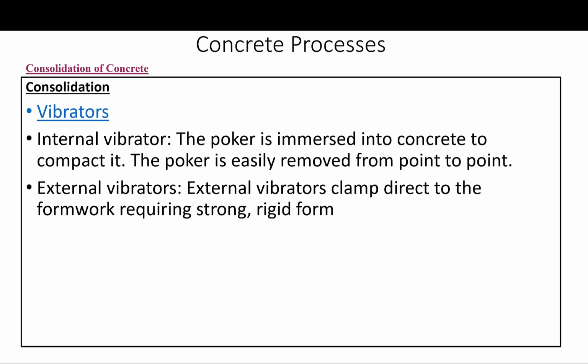Okay, vibrators. So vibrators can be external or internal vibrators. Internal vibrators, the pokers are immersed into concrete to compact it. The poker is easily removed from point to point. The external vibrators are clamped directly to the formwork. These will require strong, rigid forms. And again, before using external vibrators, you better make sure your form can handle it. You don't want to end up with a disaster there.